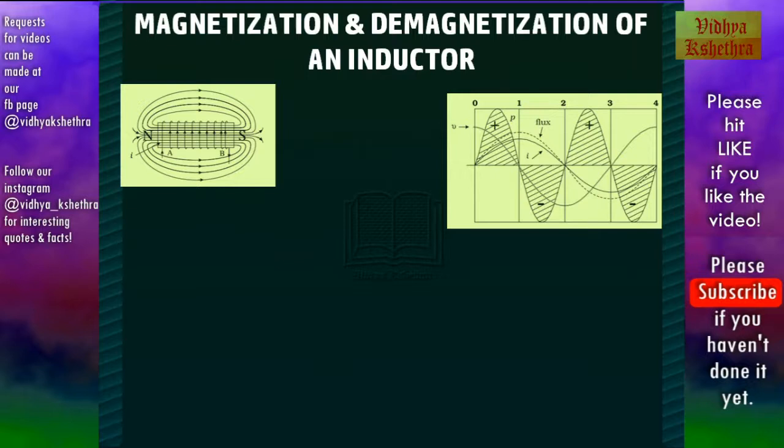And since the current is increasing, it induces a magnetic field in the core of the inductor coil. Now, in this stage, since the voltage and current are having positive values, the resultant power is also positive. Hence, energy is absorbed by the inductor from the source in this stage.